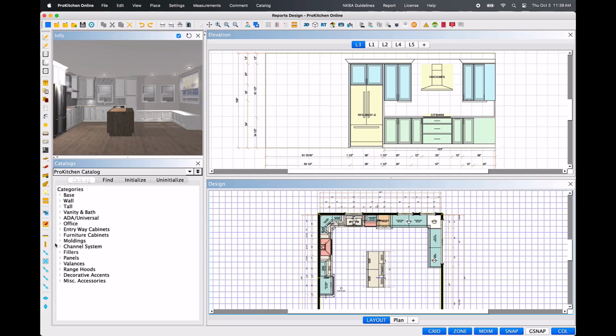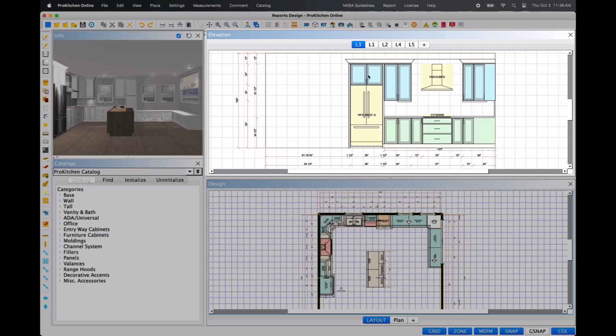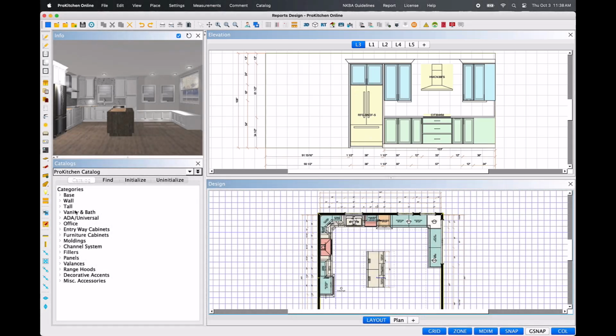At the top of the dimension tools set are two ruler icons, one horizontal and one vertical. These two tools are static in nature and will act similar to automatic user DIMs. To demonstrate these tools, I will work in the elevation view of this design. The horizontal ruler will create a user dimension that runs horizontally along the view in both the plan and elevation view. Left-click once to grab the tool.